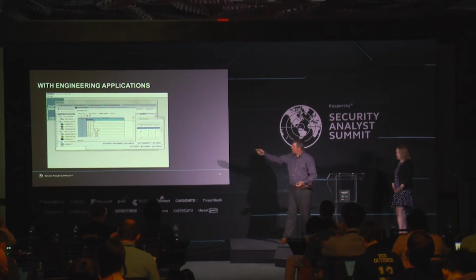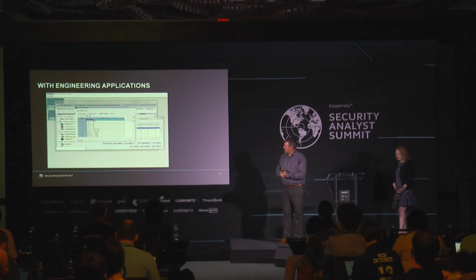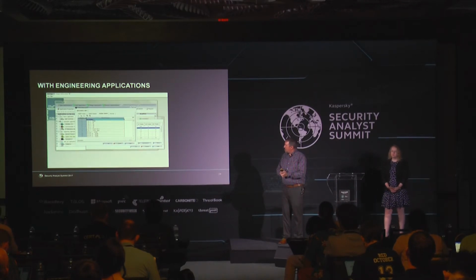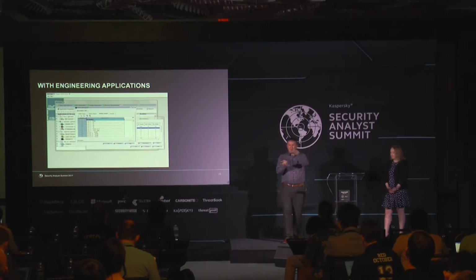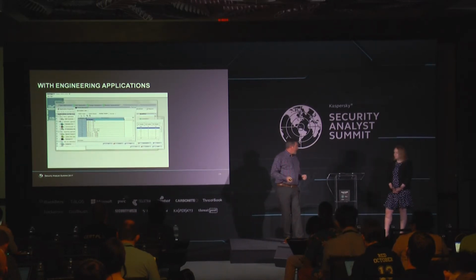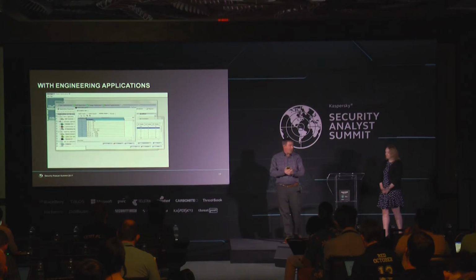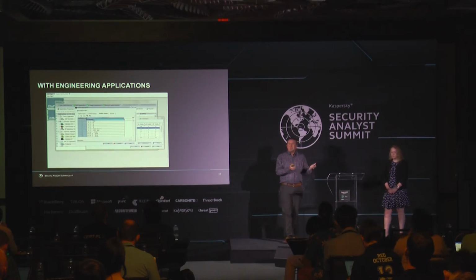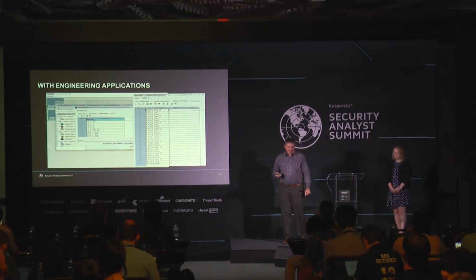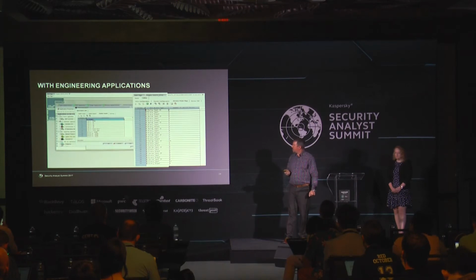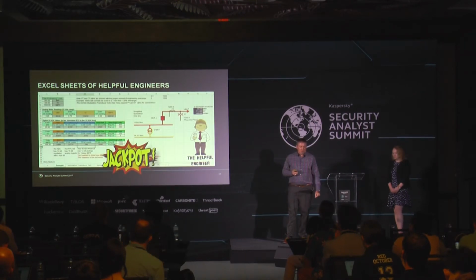And here's an example. It just shows, okay, we opened up the database in this RTU, and you see line 1 megawatts, megavars, kV. Now we understand what those point lists in DNP3 mean. Now we know that point 0, that 17 is line megawatts. So until we knew that, we didn't know what that number meant. Here's some more examples, screenshots from an example configuration tool.